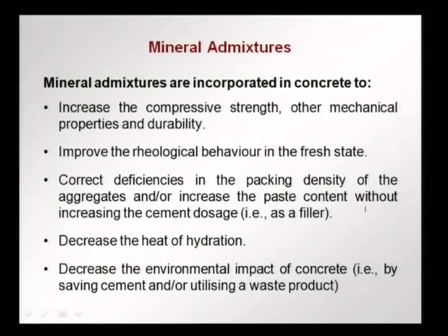In some cases the rheological behavior is also improved. You get more cohesive, more fluid concretes with the right type and amount of mineral admixtures. Mineral admixtures could also correct deficiencies in the packing density of the aggregates. If you remember, we just talked about the need to have a dense packing of aggregates, and sometimes the aggregates available may not have the right type of gradation, and for this mineral admixtures could be used.